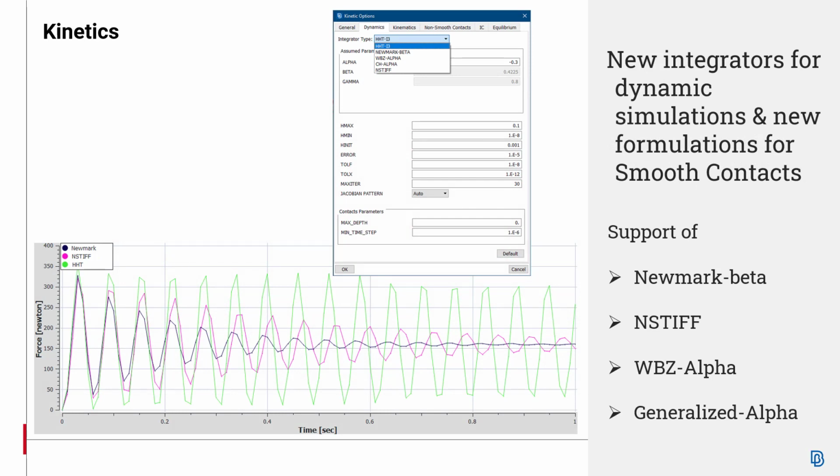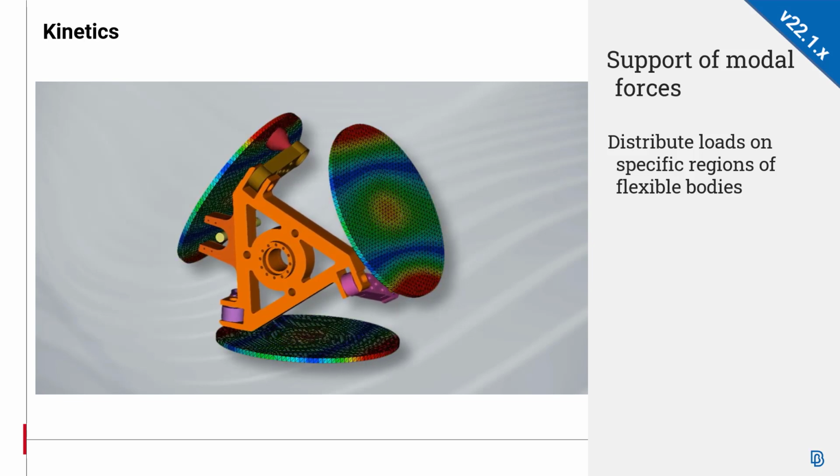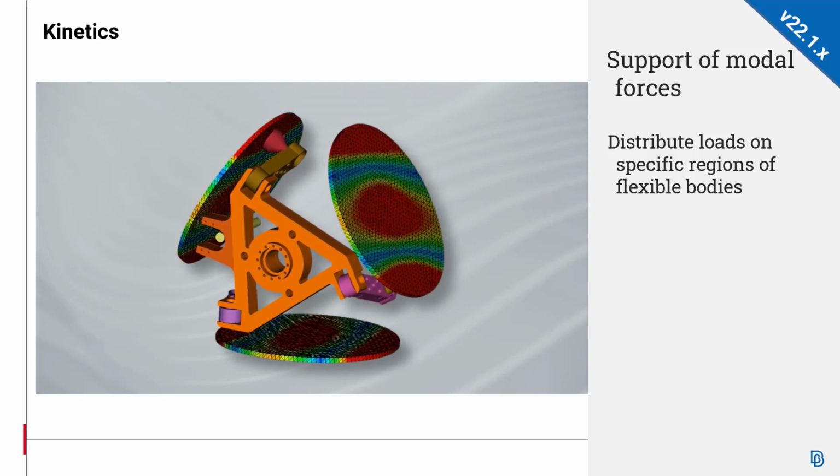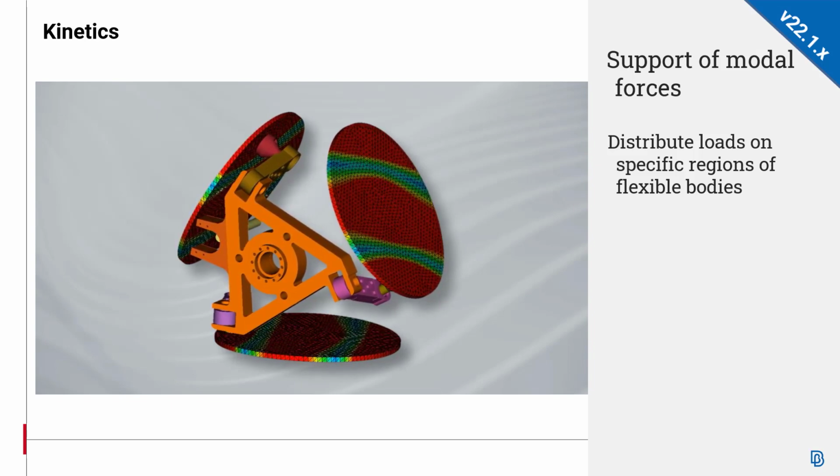New integrators are now supported for dynamic simulations to provide a wider range of integrators, while also new formulations for smooth contacts, namely impact hysteresis and restitution, are now supported. A new type of force called modal force is now supported for applying time-varying distributed loads on specific regions of flexible bodies.